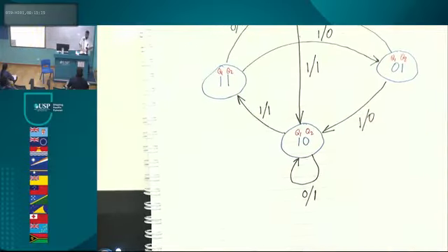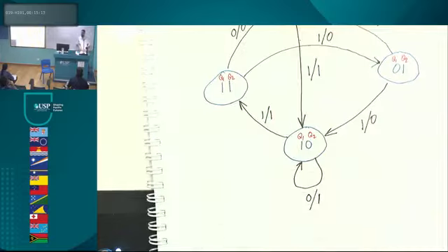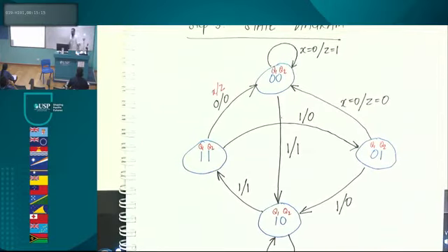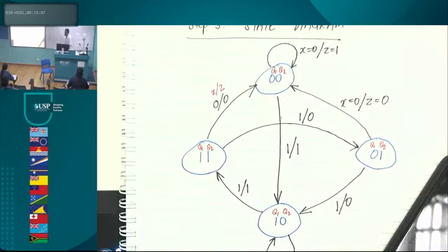Then we came up with this. Eventually, you end up with the state diagram. In an analysis problem, you finish off with the state diagram, but if the state diagram is depicting some clear behavior, say 0, 0, 0, 1, 1, 0, 1, 1, going all in one direction, then you could say, hey, this is just a counter going from 0 to 3 and then returning, right? But sometimes it's going all havoc, so there's no clear behavior over here, right?